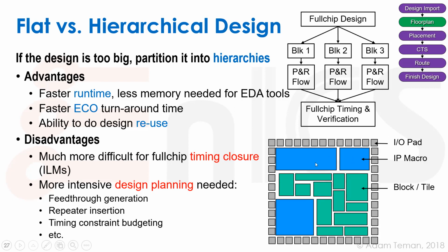So what are the disadvantages of doing this? Well, it's much more difficult for full chip timing closure, and I'll discuss in a second what an ILM is. There's more intensive design planning needed. We need to think about how we made this chip from the beginning. We may have these types of feed-throughs. For example, let's say that this is the clock pin, or maybe this is a pin that gives a voltage that goes over to here or over to here.